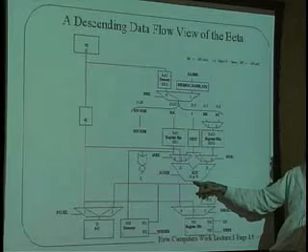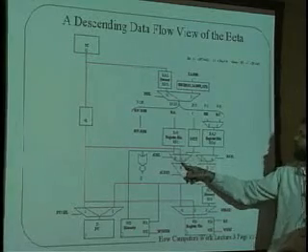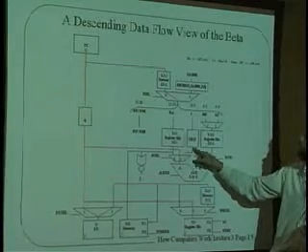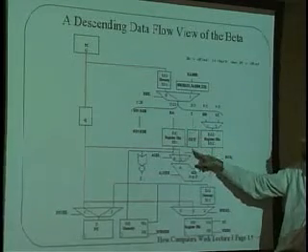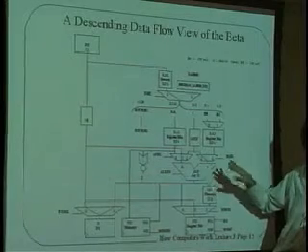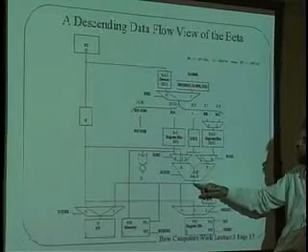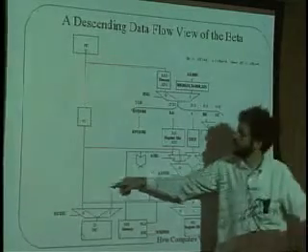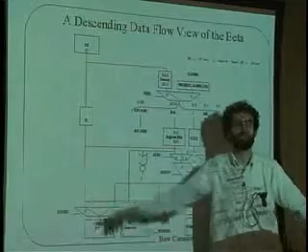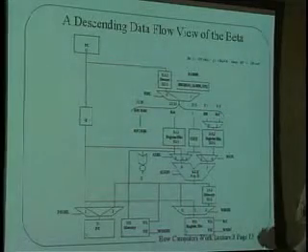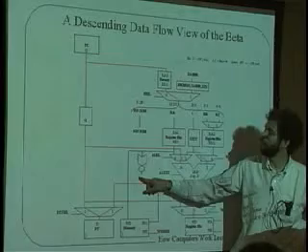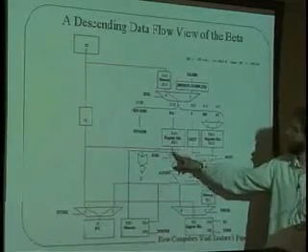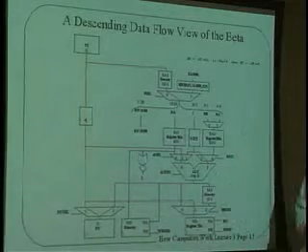And what's going to pop out of the ALU is going to be PC plus 1 plus, and we're going to set this to plus, what comes out of this path, which is the sign extended constant C. So the ALU will be told to do an add, and the result of the add of PC plus 1 plus C will be spit out here, and that will go into the PC instead of PC plus 1. And the control over that will be whether or not this little Z here is high or low. In other words, whether the data that's coming out of register A over here is all zeros or whether it's not.